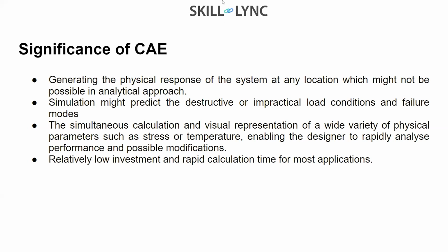Other than this, simulations might predict destructive or impractical load conditions and failure modes. So at a certain point in time, it may predict impractical loading conditions and failure modes. You should always be clear about what boundary conditions you have to use, and what mesh types you should use. We will cover that later on in this webinar, but first and foremost, you should understand what type of loads you should use as a boundary condition.